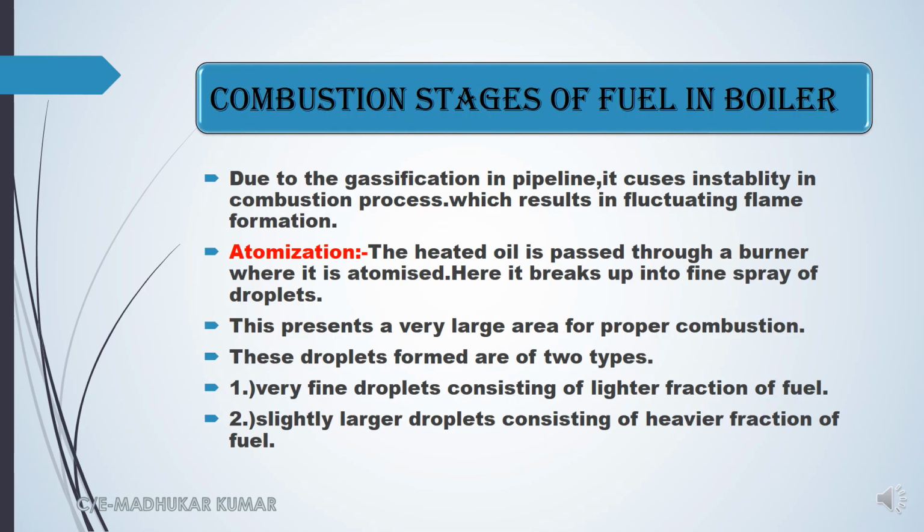Again, due to the gasification in pipeline, it causes the instability in combustion process as the result in fluctuating flame formation. So we have the gaseous formation, less fuel is going, and the fluctuating flame is also being produced. And after that, if it continues for longer time, then flame trip is also happening. This is also quite possible.